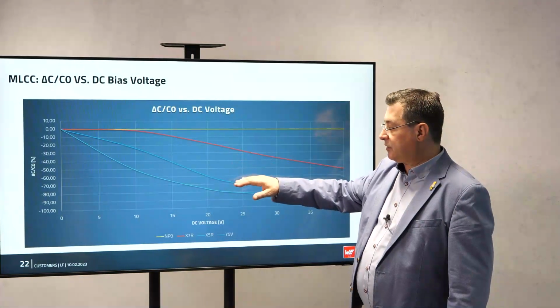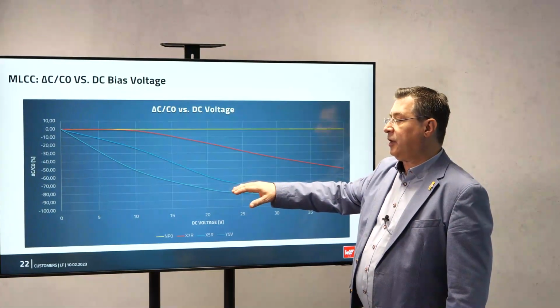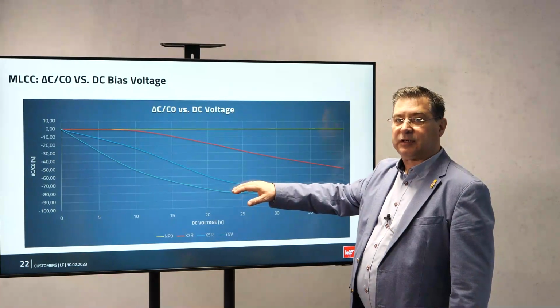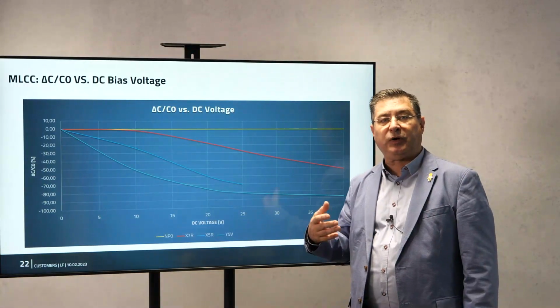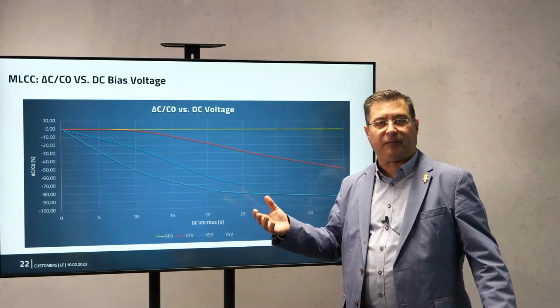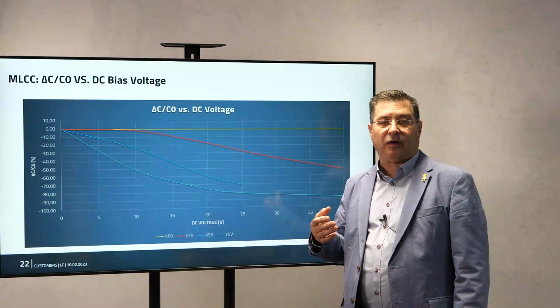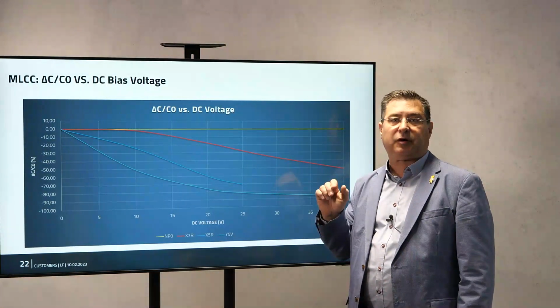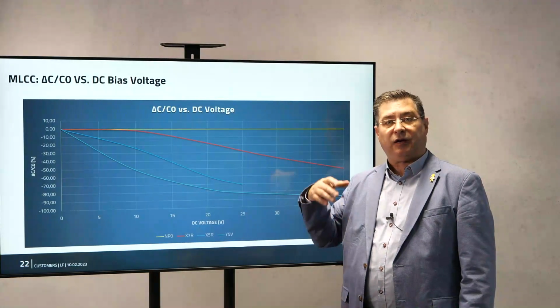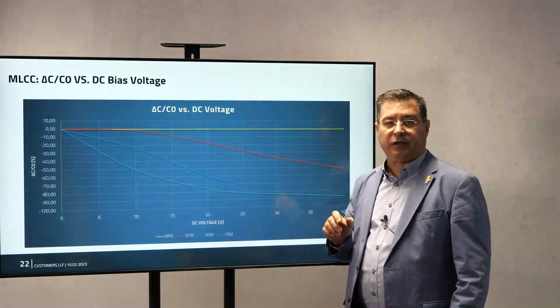If you choose an X5R it will drop more like 60-70%. So it is just the information that this capacitor can withstand this 50 volt, but doesn't give you information that it will be 100% half the value. So think about by the capacitor selection, if you need 100 nano, which dielectric you have to use.